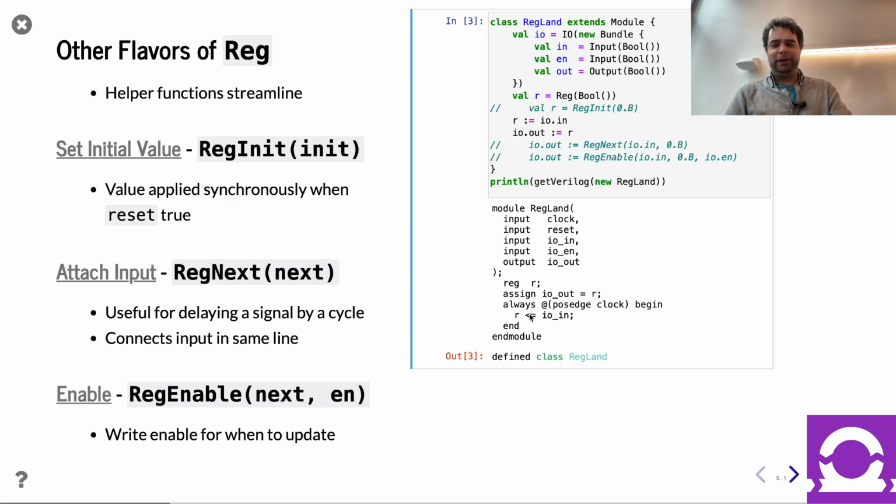And so you can see in Verilog, it's a little bit more indirect, right? In Verilog, there's this reg construct, which despite seeming similar to register, when you use reg in Verilog, you are not guaranteed to get a register, right? There's plenty of ways to use reg to get purely combinational logic. Reg is simply a construct that means you're allowed to assign it in certain ways. And whether or not it turns into a register or latch in Verilog depends on how you use it within an always block. And so guess what? All that complexity you may have learned, blocking, non-blocking assignment, all that stuff, is not needed for this course.